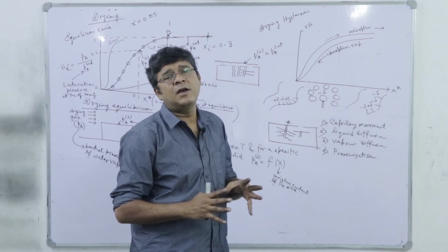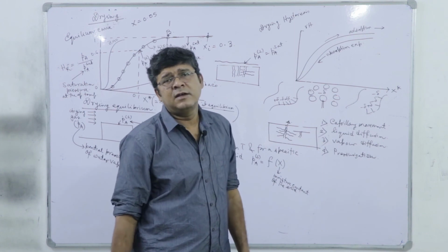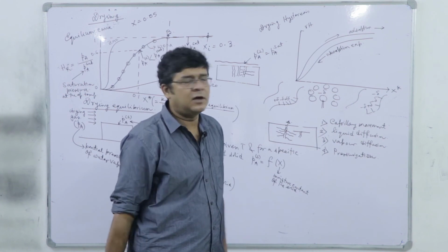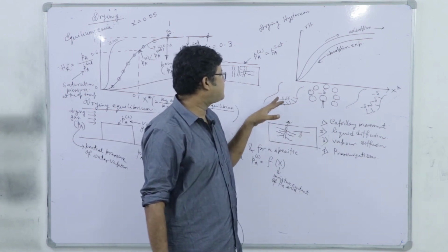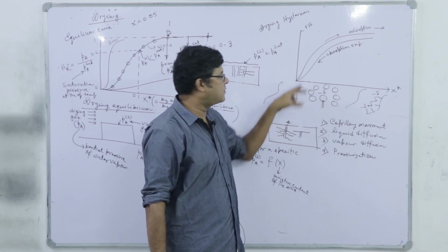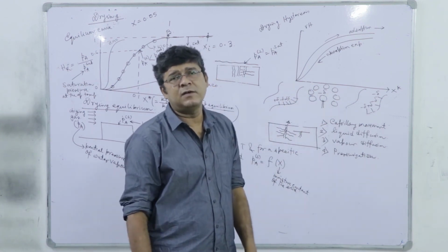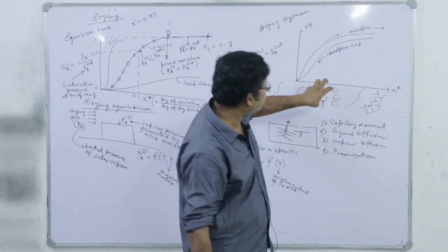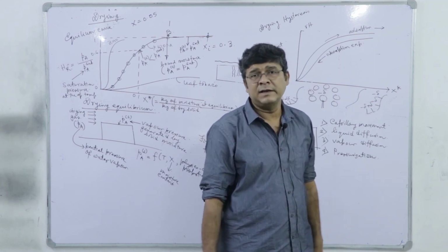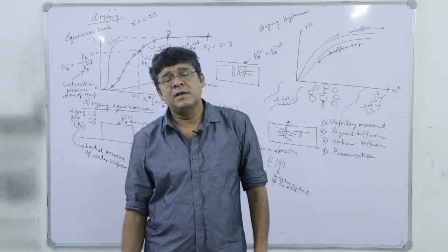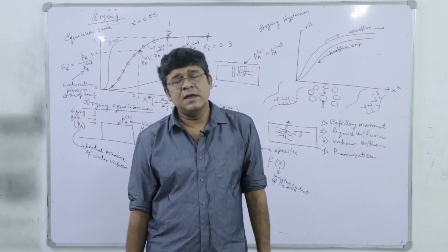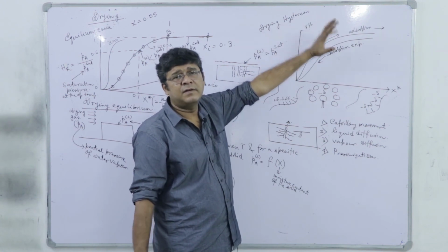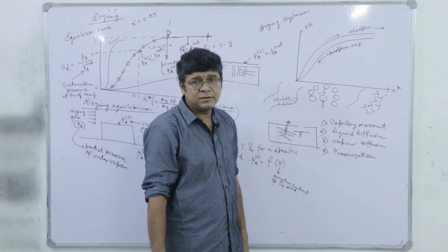But this is not going to change in the case of a desorption experiment, because in a desorption experiment we always start with a solid containing unbound moisture. There is a film on the external surface. So, these surface functional groups are hydrated at the beginning of the experiment, and the water holding capacity may be higher or lower, or at least different from that of a bone dry solid, because the capillary morphology is different due to this hydration effect. And that is why we have hysteresis. That is a crude physicochemical reasoning behind this drying hysteresis.